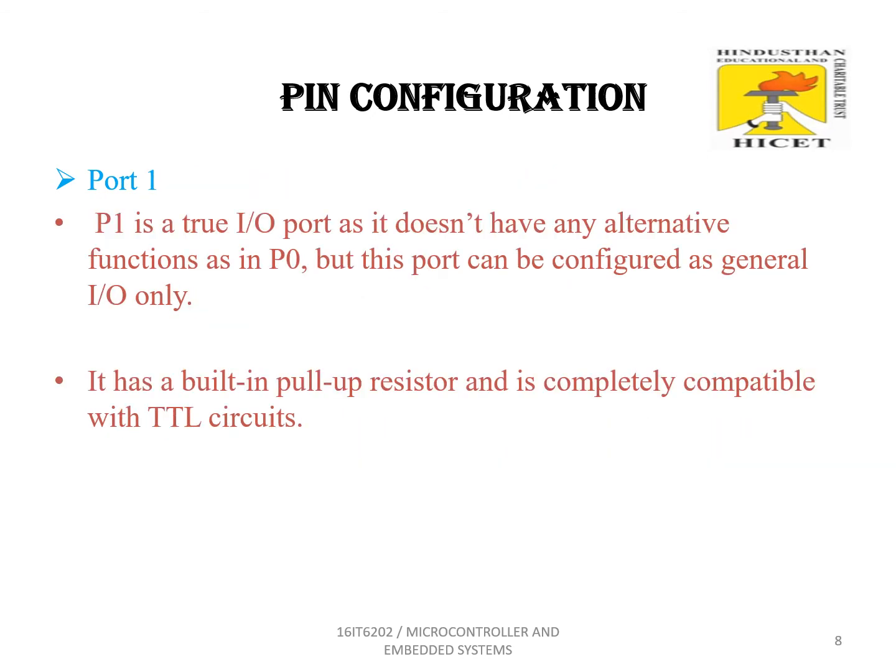Coming to the next port, port 1. Port 1 is a true input output port as it does not have any alternative functions as in port 0. This port can be configured as general input output only. It has built-in pull-up resistors and it is completely compatible with TTL circuits. TTL stands for transistor-transistor logic circuits.